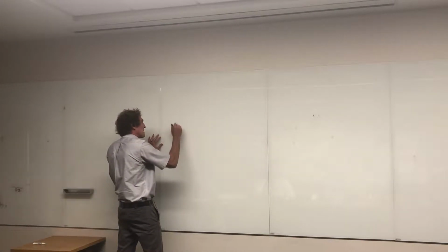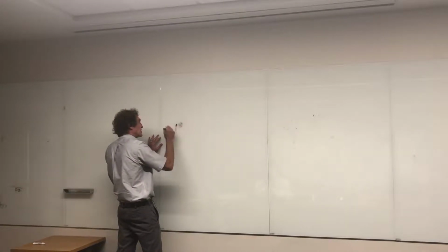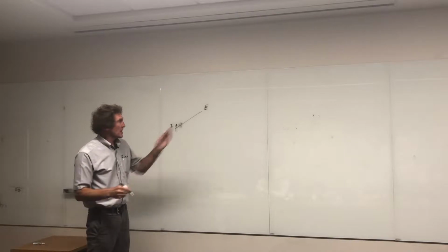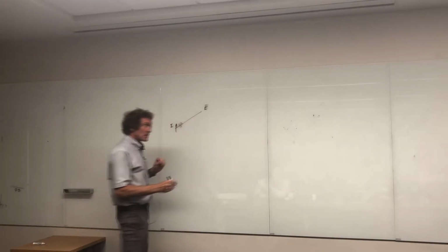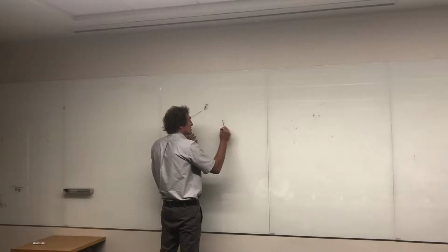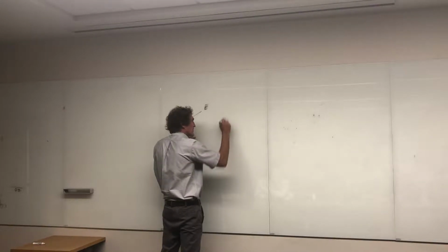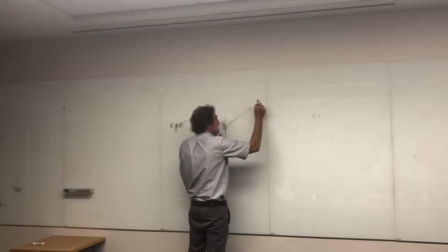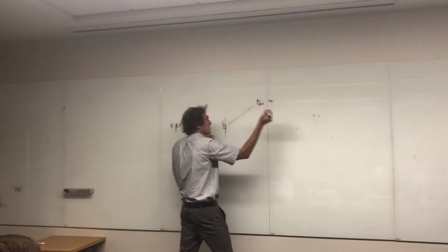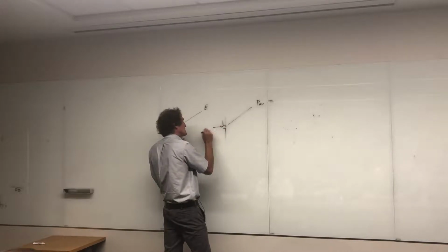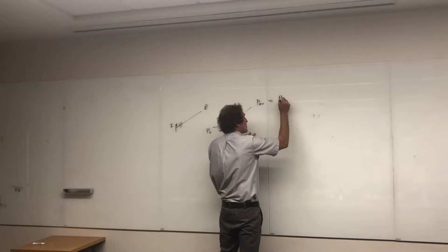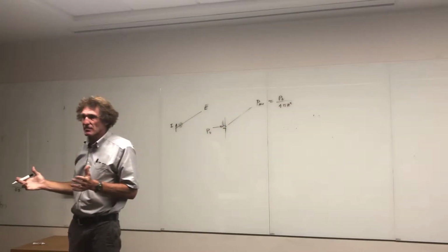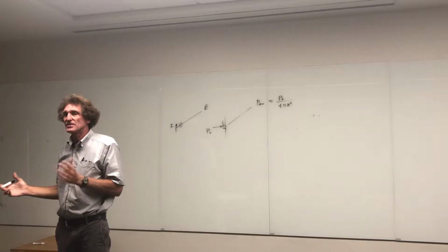If you have just an antenna right here, an antenna with a current I, we know that there's going to be an E field out here, right? If I want to know the electric field or the power, better yet, let's do the power density, P_AV out here, if there's a total power P total going in, that's equal to P total over 4 pi R squared. Now that's isotropically distributed power. Do you all agree with me? It's the same amount of power in every single direction.